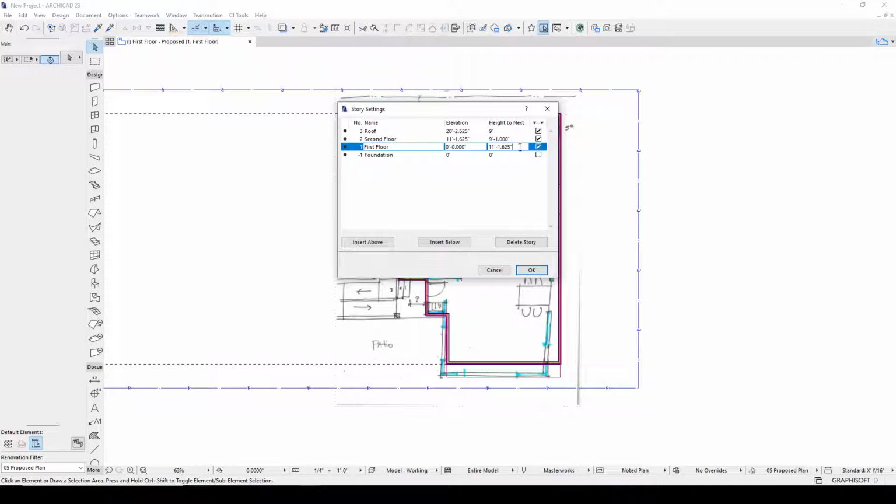And depending on what sort of joists we're using, we need to allow for the exact dimensions. Now we're using engineered I-joists most of the time, so this looks like it's set up for 11 7/8, 10'1" wall, 11 7/8 joist, 3/4 inch of plywood. So it's not the wall height. This is actually the floor to floor height. So this is assuming a 10'1" plate, 11 7/8 joist. This is a single story.